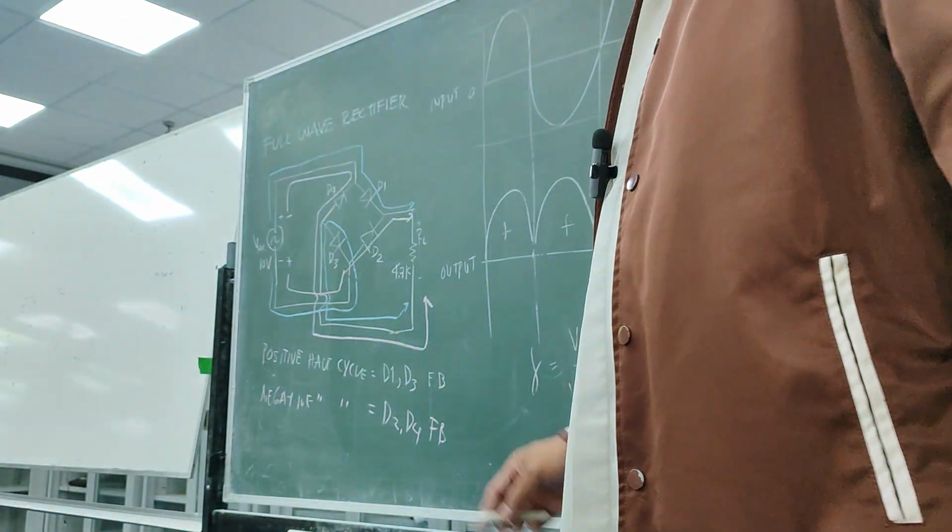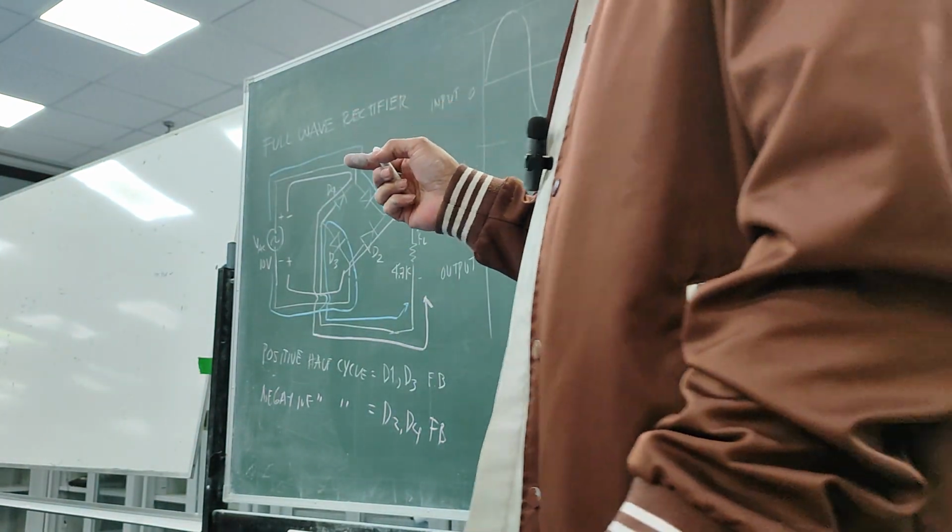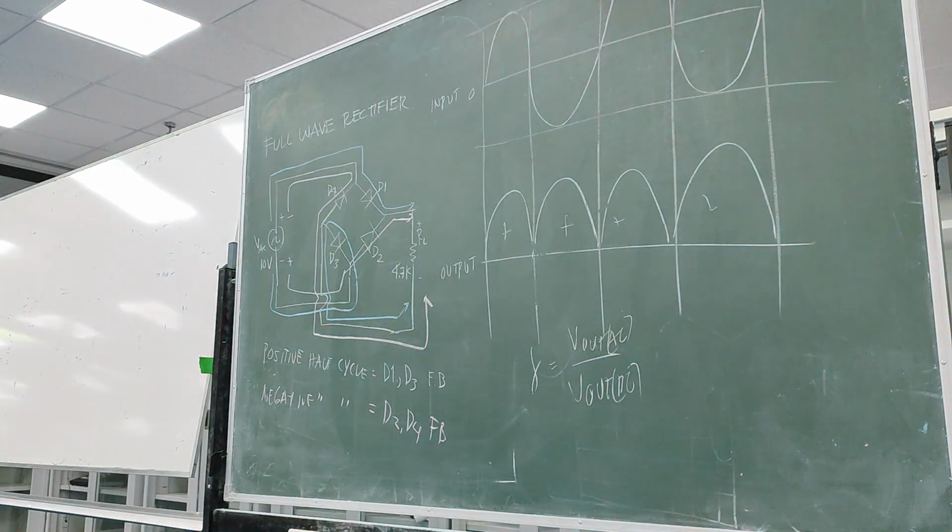And also, remember I told you last time about the DMM. When you are using the DMM, what you are measuring is in RMS values, but it's not shown in the book. You will be wondering why the value of the waveform voltage is different from the value that you measured using the DMM. The value measured using the waveform is bigger compared to the DMM value.